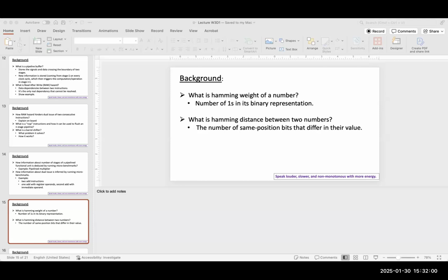So they want to answer these questions: in this CPU, how many ALUs are present? And can they all compute all the functions? All the functions means, if you have an ALU, can it do addition? Can it do logical operations? Can it do multiplication? And so forth, right? Or maybe it is the case that only one ALU can do the multiplication and the other cannot? Okay. Second, are units performing multi-cycle instructions, for example multiply, shift, LDR, STR, etc., pipelined or not?